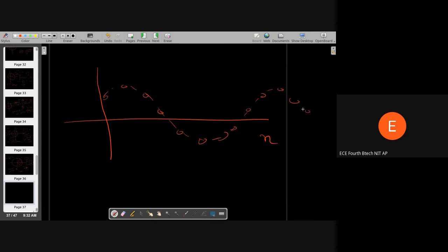If you give a signal of the same frequency as its characteristic resonant frequency, it will blast and produce a huge output. So it's the same kind of concept here. A sinusoid never dies down. It's infinite. So along with the resonator, we got z minus z1, z minus z1 star.